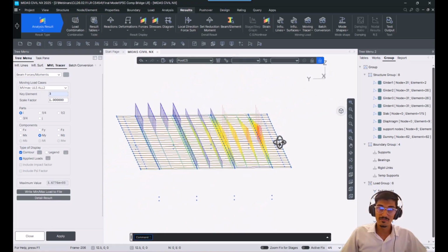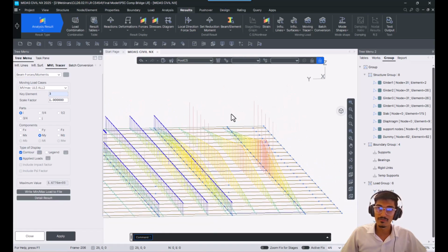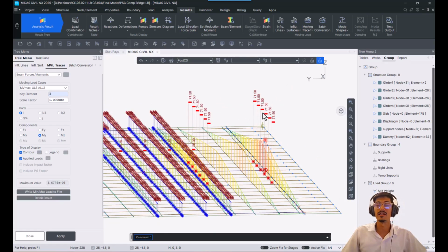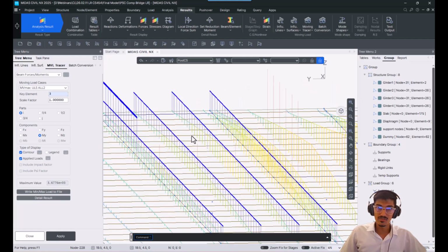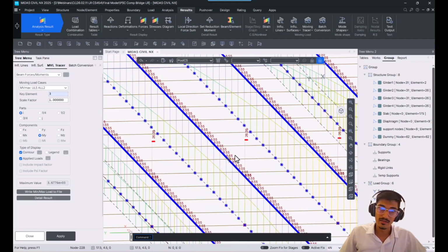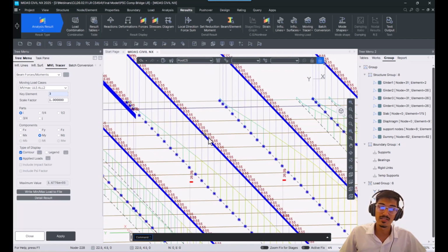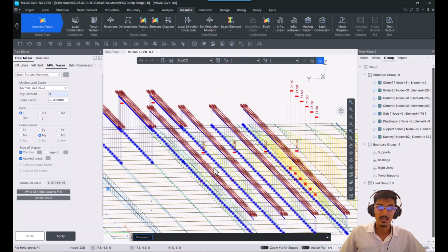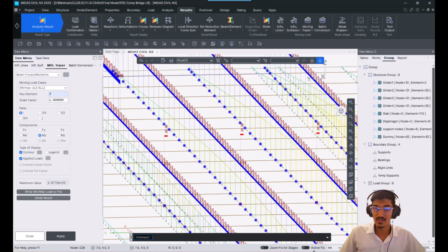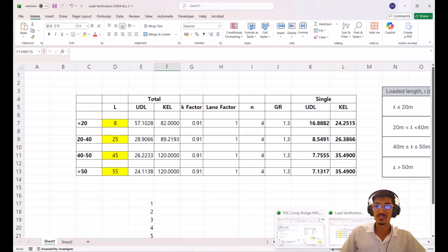So firstly, the special vehicle is pretty straightforward. If we see, it has applied a factor of 1.1, that is what we had defined for the load effects. For the others, if you want to verify the loads like this 26.39 and where this 8.55 has come from, we can also verify them by checking the Excel, and the code has prescribed the values.